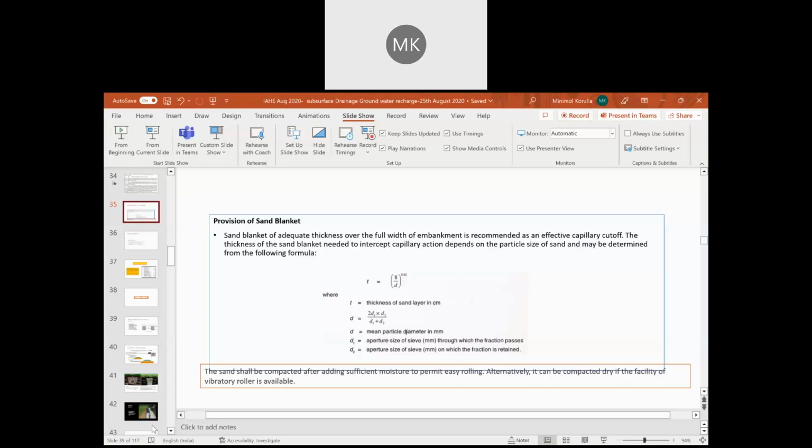Consider only a 25-year return period for a normal district road or a state road. Even for the 25-year return period, considering the type of discharge intensity we have to consider, if we design a drain, the depth and width will be much more than what may be assumed. So it's a big jump, a big jump in cost effectiveness as well as in the reduction of natural destruction.